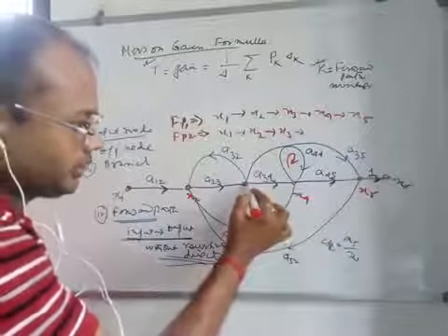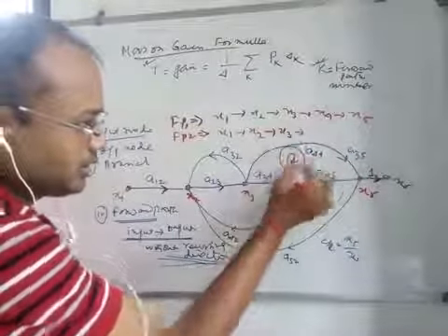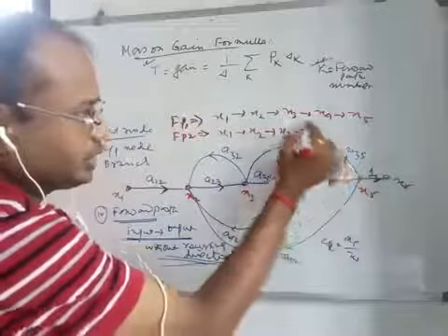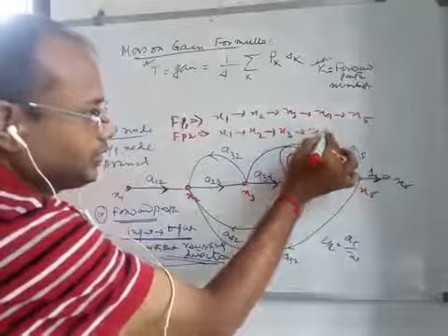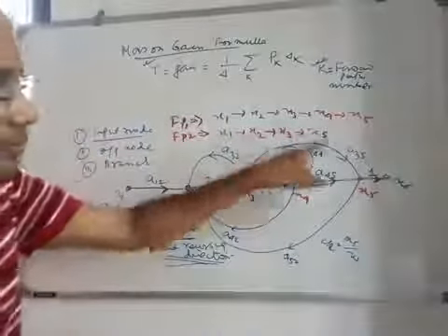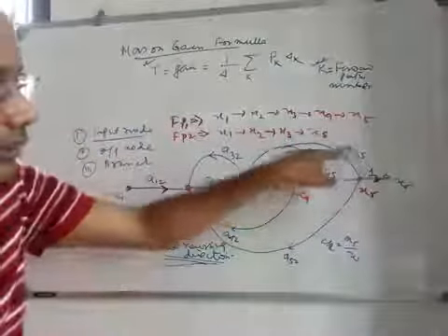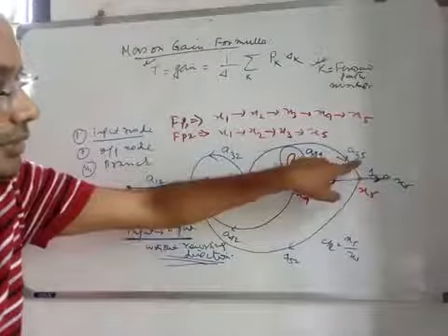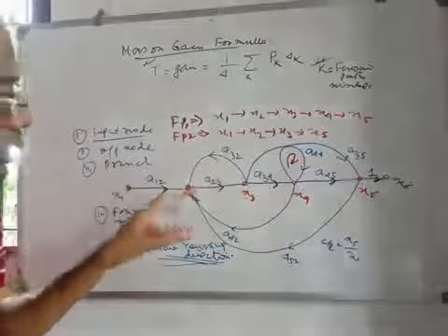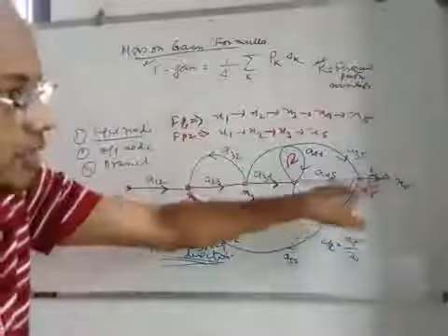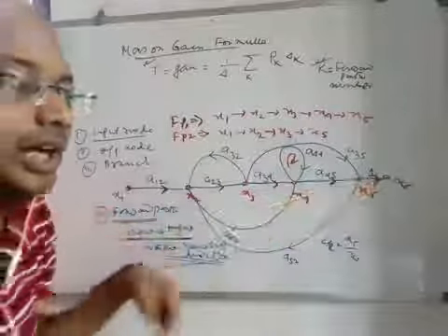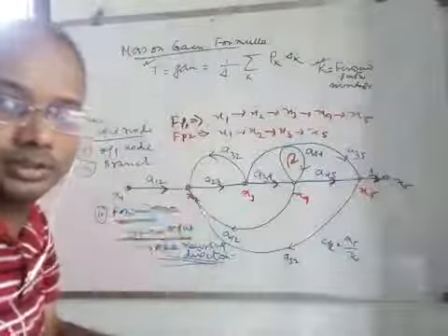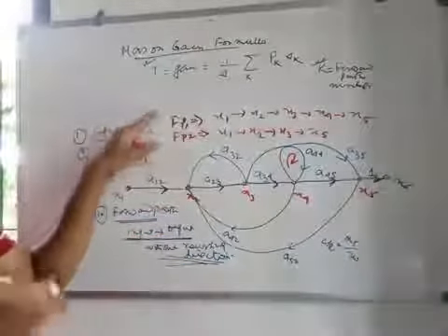So there is another path, say bypassing. See the direction a35, so x5 via a35, right? That means x1 to x2, x2 to x3, x3 to x5, without changing the direction and without traversing a single node twice. So that gives you the concept of forward path.